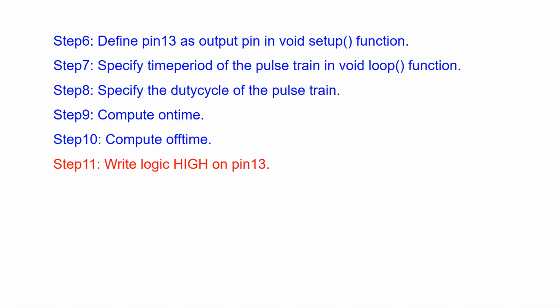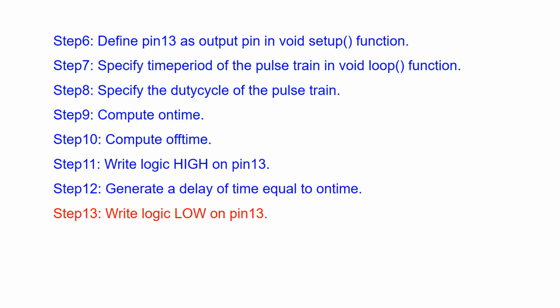Step 11. Write logic high on pin 13. Step 12. Generate a delay of time equal to on time milliseconds. Step 13. Write logic low on pin 13.